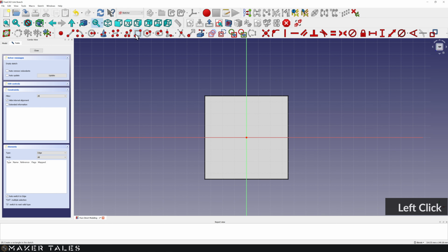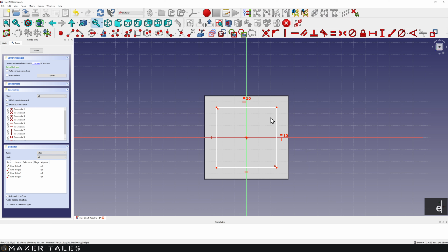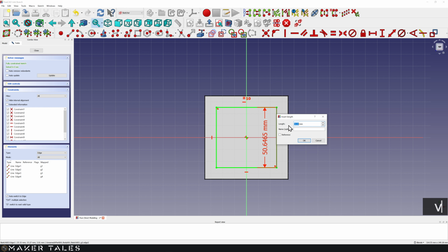Create a sketch, create the rectangle, select the points, make it symmetrical, make these equal, add the dimension. Now the dimension might be a little bit weird for you here, but basically it's because there's a bit of an offset. So you can just look at the technical drawing. It says 66.2, but I just want to explain what's going on here.